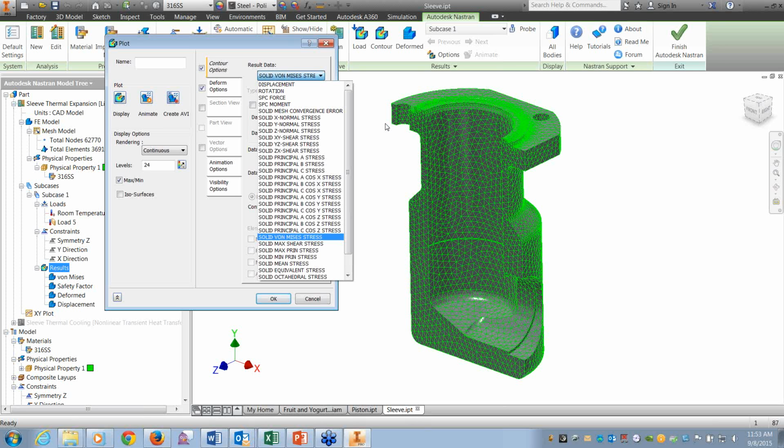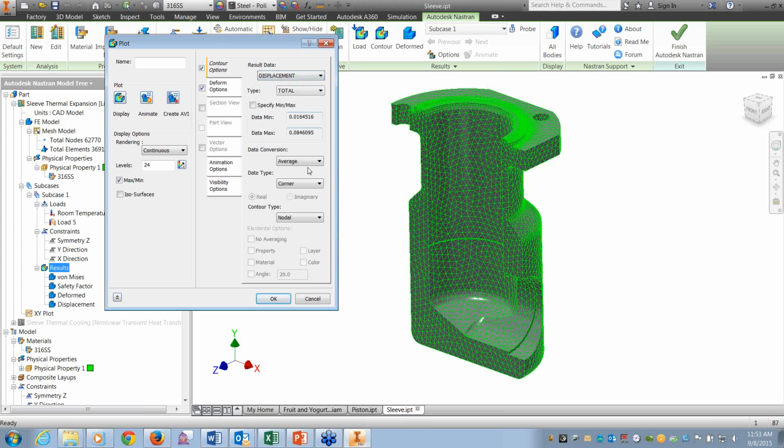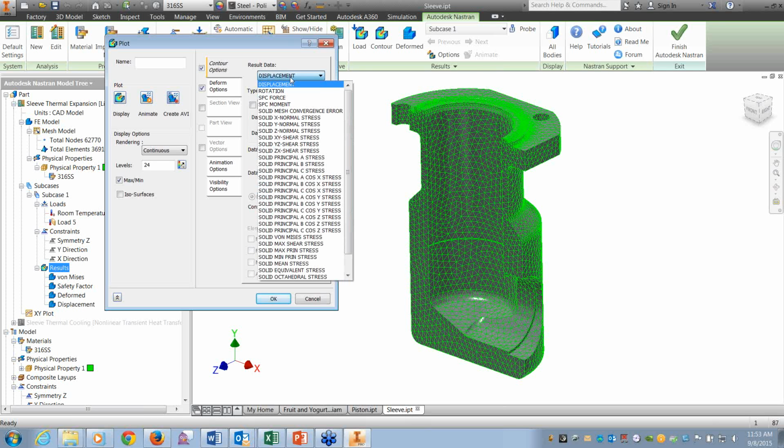And if you attend one of my classes, you're going to hear this preached at you. Always look at displacements first, because it's how you check to see whether or not you have things locked in place right, or did this 1 ounce of force send it into orbit around the moon. You know, a quick sanity check there. But there's a wide range of options available to you.